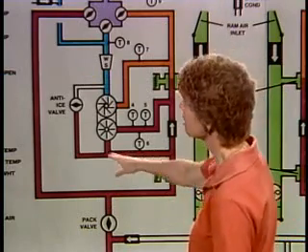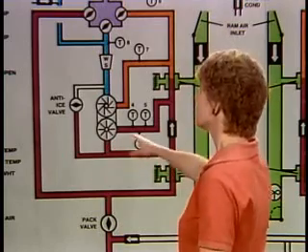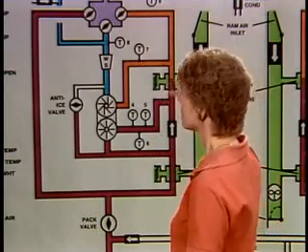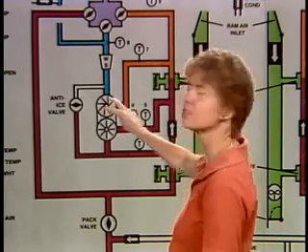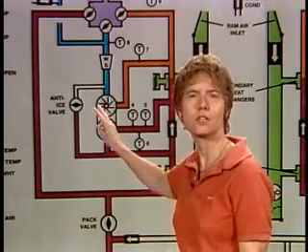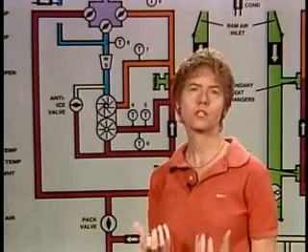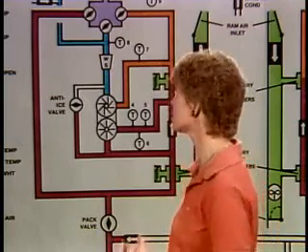Then it continues along and goes through a compressor, continues on, goes through a secondary heat exchanger, continues on and gets to here, which is the expansion turbine, a very critical, important part of the air cycle cooling system, because the air cycle cooling system basically produces its cold air by extracting heat energy across an expansion turbine.